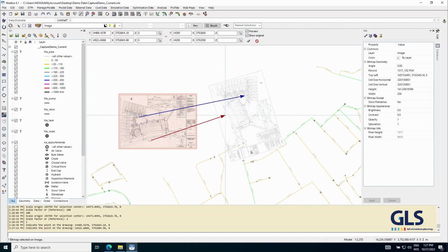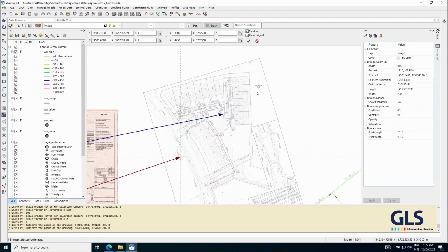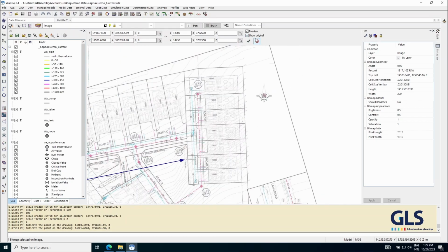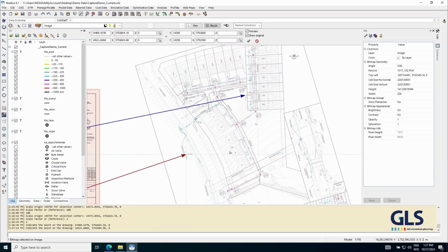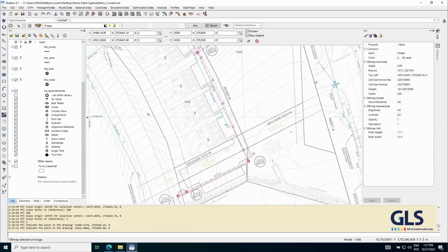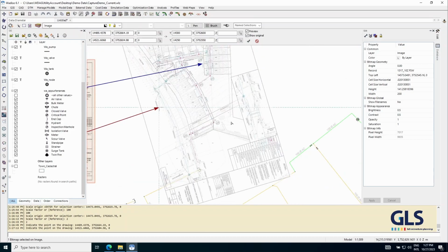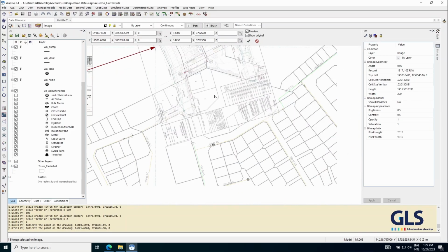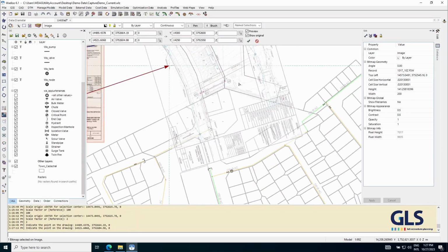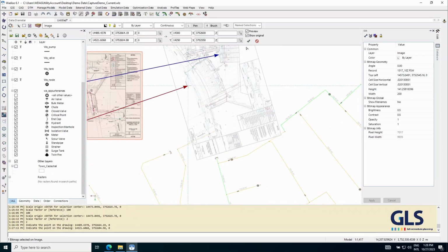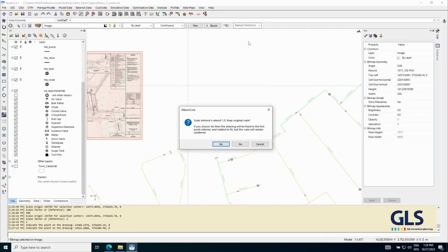We can also do a preview. So on the preview, you can already see that the north arrow is now pointing to the expected north, or up in case of a world space. And again, if we have additional information like the boundaries that we have there, because this is a real world known example, we can turn those on, and then we can actually see that they do overlap quite well with what is in the image, so we can be happy that this reorientation is correct. And click the OK button.